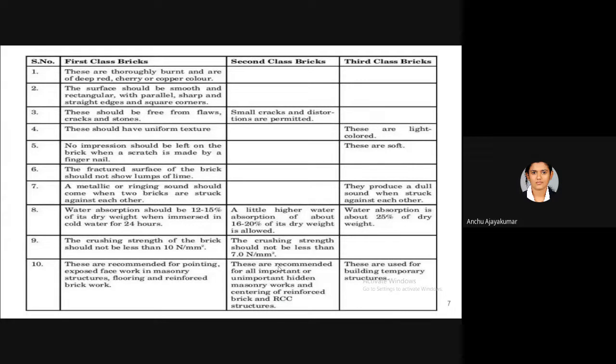And what is first class brick? The good quality bricks used for load bearing walls or whatever it is are classified under first class bricks. So you have to note the water absorption of these 3 classes of bricks for your question, and the crushing strength, how it belongs to first class or second class according to the crushing strength and all. And for this work, what class of brick are you using? That is the question that you can expect from here.